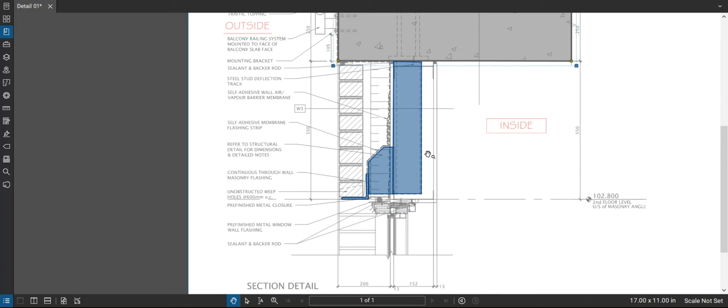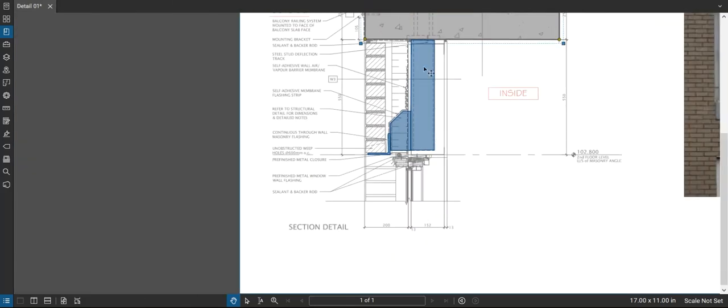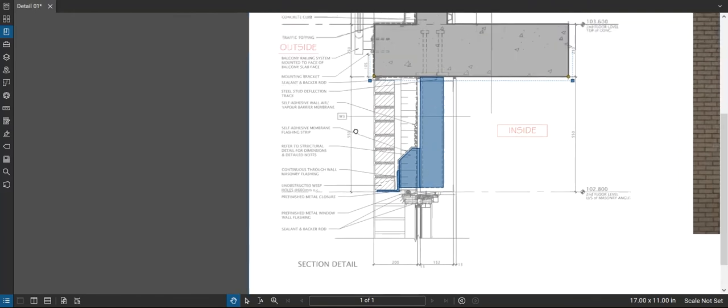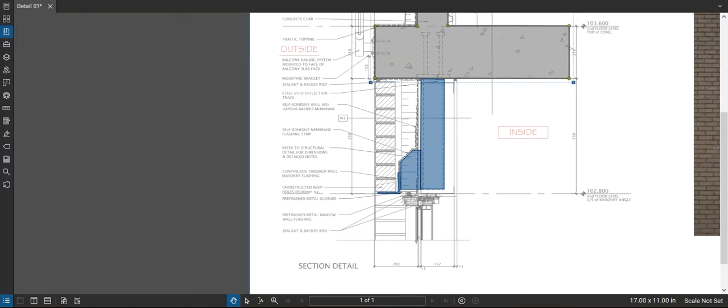And of course, do you need that always when you're hanging down steel studs? Not necessarily. If this window wasn't too big and there were continuous studs on each side of the opening, and the opening wasn't too wide, then it would probably be okay. But nonetheless, it could be offering some more structural support there than I first mentioned.